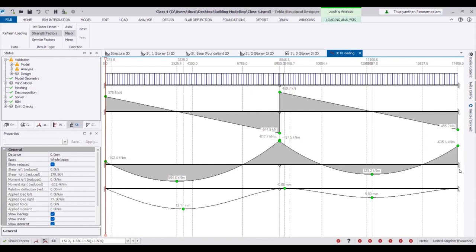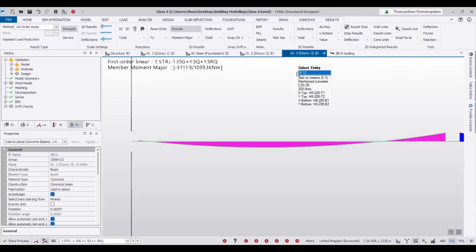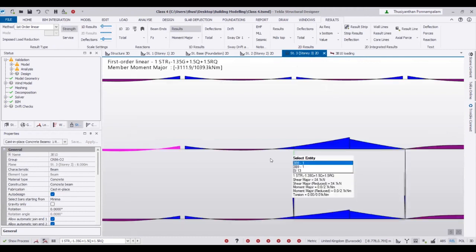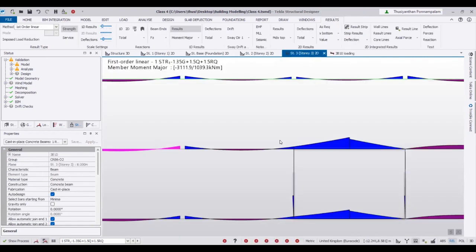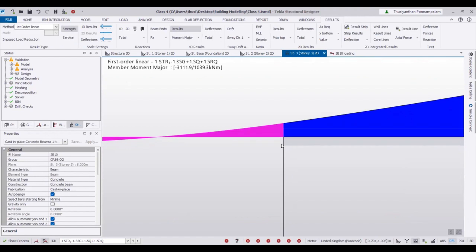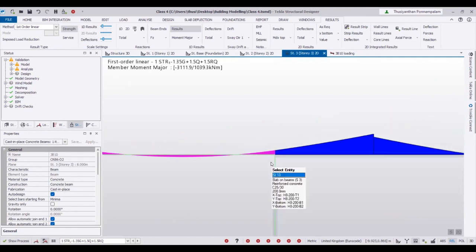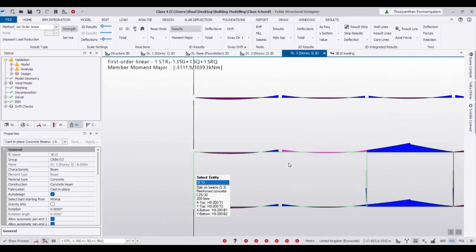So these are the things. If you do it like this, then we have to be careful when we do the joints. When we do these joints, the second span, this joint or this joint, these joints, we have to be careful on this joint. So that's why, as much as possible, at the end one we have to make it pin.